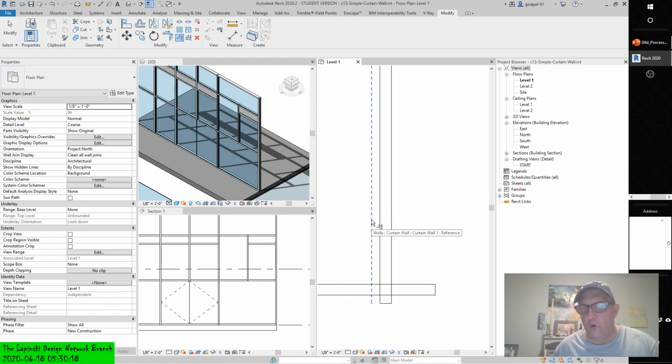Well, this is the wall, the curtain wall delineation line. It's core, if you will. And this can be a tricky tool with certain elements. So select the side you want to keep. Select the trim line. Click a wall on the part you want to keep.